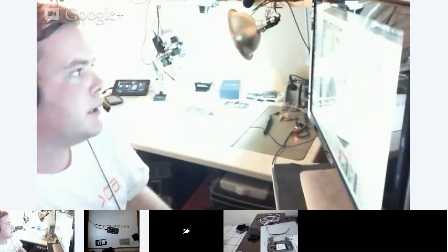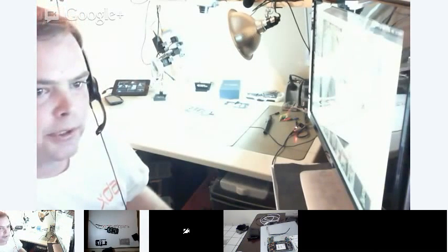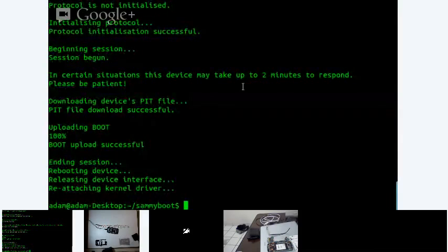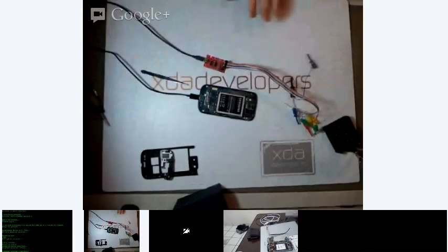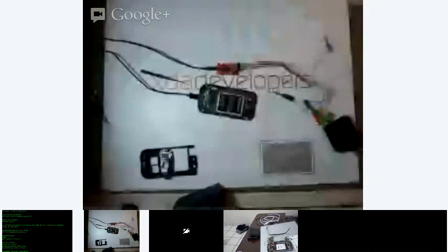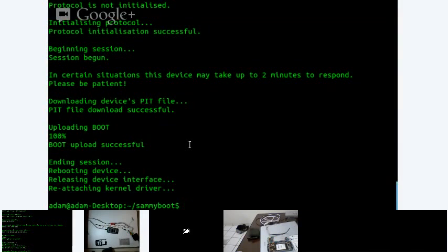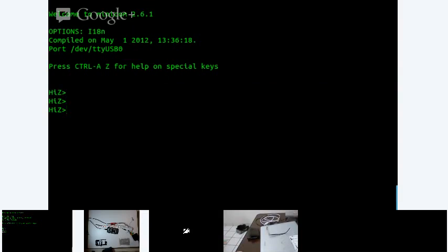So the next thing we want to do is turn on the UART device that we're going to be using to communicate with this. I'm using a Bus Pirate. That's this device right here. Let me switch back over here, and the way to initialize the Bus Pirate is I use minicom -D /dev/ttyUSB0. All right, good.